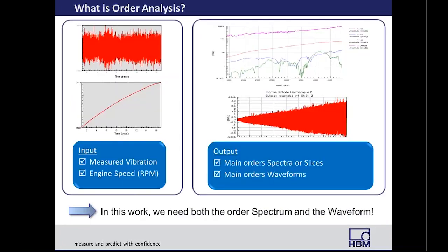First, what is an order and what is order analysis? Well, rotating machines generate vibrations due to detonations in cylinders, balancing issues, or misalignments of rotating axes. And vibration may vary proportionally with the speed of the main shaft. They do vary proportionally with it. And multiples of the fundamental speed are called harmonics or orders. So the order tracking objective is to identify the various orders that are effectively buried in the signal and extract their characteristics.